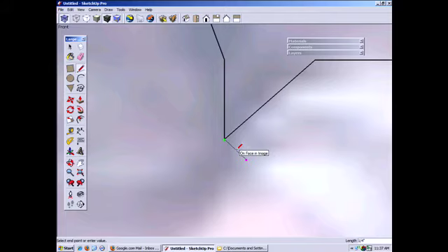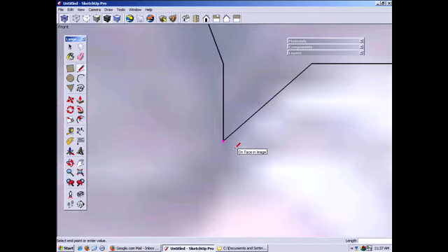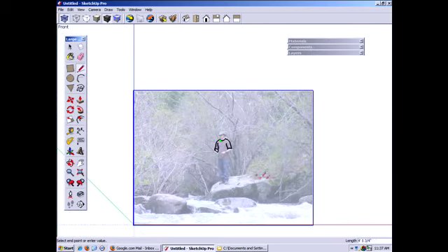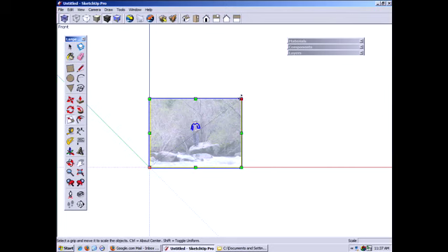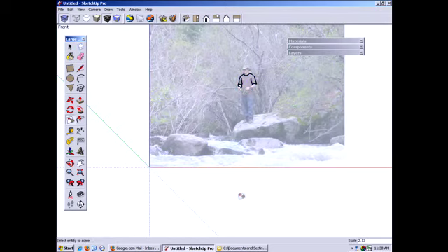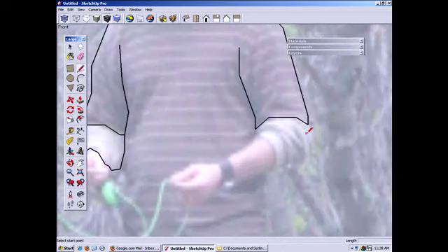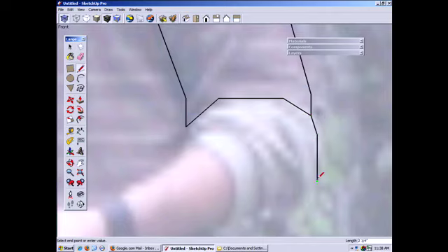Now I talked about, I'm not worried about scale as of yet. Based on the template you've chosen, if you want to put more detail in here, I'm snapping to every quarter inch, meaning that I can't put any more detail than that in. Again, without worrying about scale, I'm just going to grab everything and scale it up so that I don't have to worry about that, or I could change my units, but I can go to the front view and create this. Some people like to use the freehand tool with something like a Wacom tablet and then trace these over. I don't like the freehand tool. Those of you who are in the basics class know that. I don't like it at all. Not even for this, because it just doesn't give me the control I want.